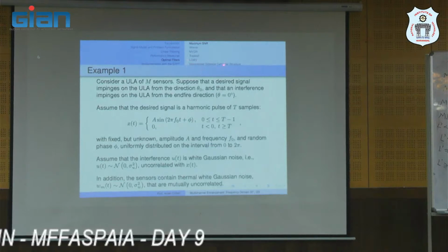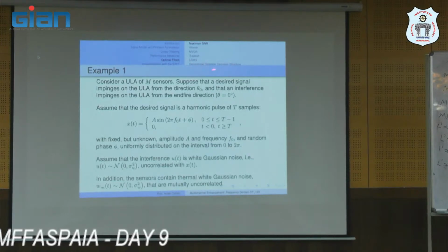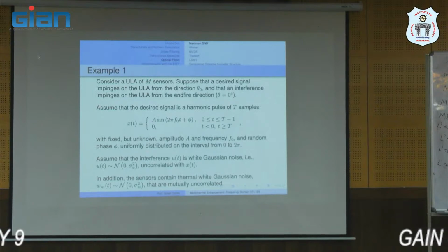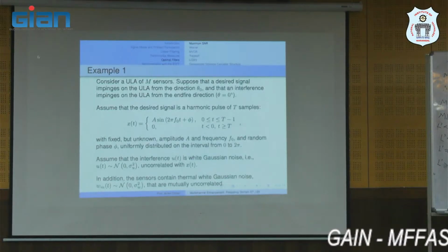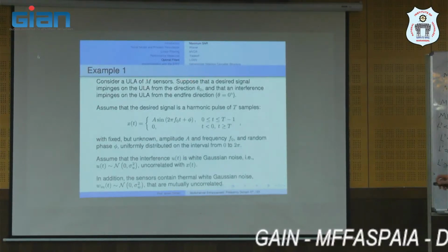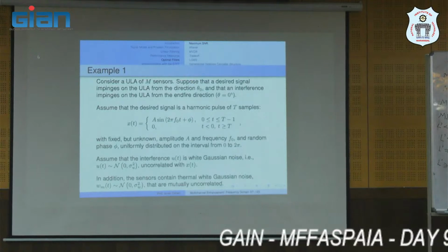And then we talked about the generalized sidelobe canceller structure that actually enables us to implement LCMV and MVDR by using adaptive filtering. We talked about adaptive filtering and its advantages in real implementations, real problems. Okay, so this is with signal enhancement.